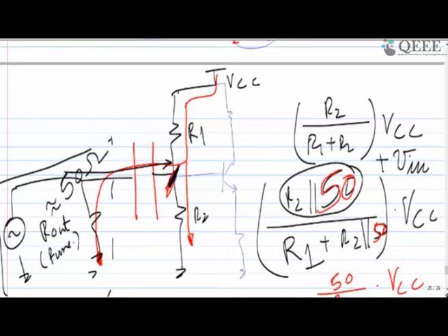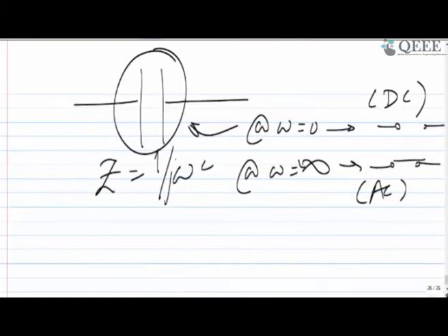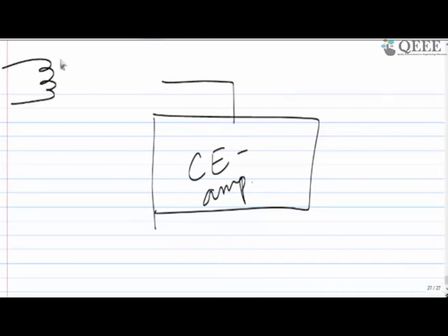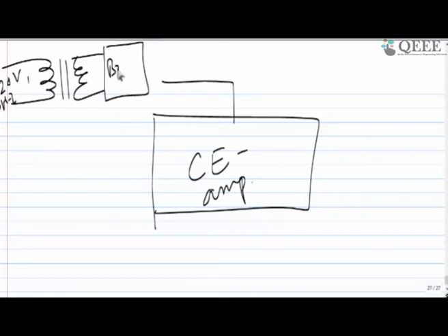Similarly, I can add some more things; for completeness I can tell you one more thing. The circuit which we have made is called a common emitter amplifier, and here VCC was coming from the very popular 220 volt 50 hertz supply for India, and there is a bridge rectifier, and the output of that one will give you a DC value.